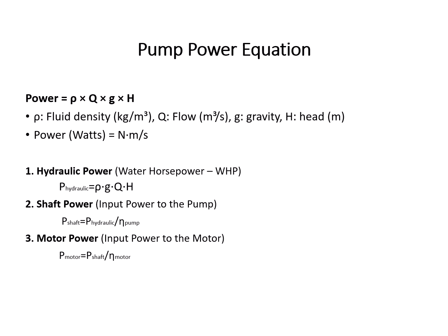Pump power equation. Let's translate pump action into mass. This formula: power is equal to rho, the density of the fluid, times Q, the flow rate, times g, acceleration due to gravity, times H, which is head.